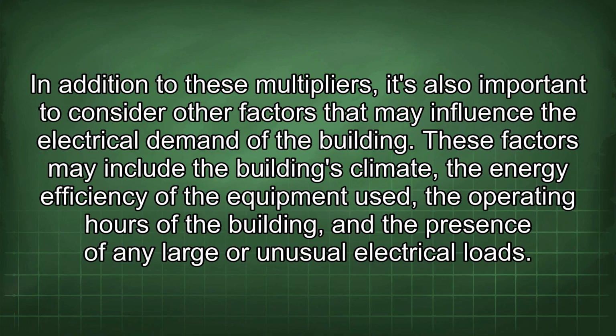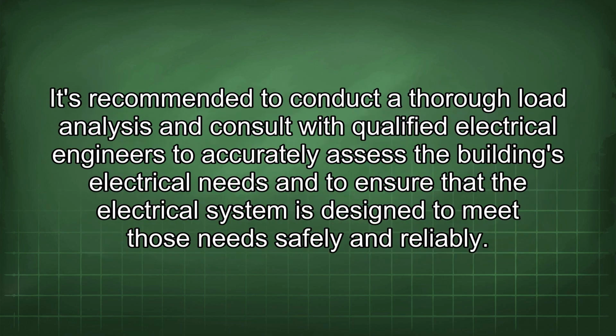In addition to these multipliers, it's also important to consider other factors that may influence the electrical demand of the building. These factors may include the building's climate, the energy efficiency of the equipment used, the operating hours of the building, and the presence of any large or unusual electrical loads. It's recommended to conduct a thorough load analysis and consult with qualified electrical engineers to accurately assess the building's electrical needs and to ensure that the electrical system is designed to meet those needs safely and reliably.